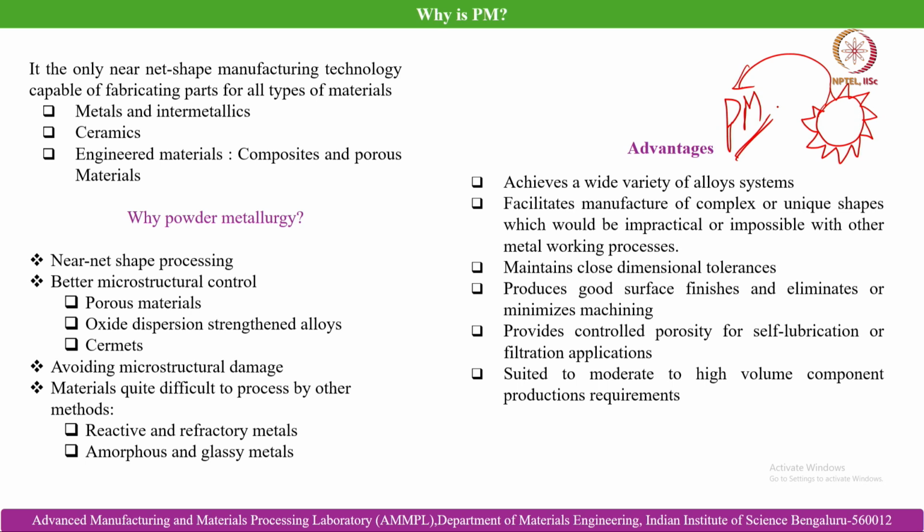In a much more economical manner. So the benefits are economic, and also in terms of properties, because we are talking about an additive route of manufacturing, so there is minimal wastage, and also better control of the microstructural morphology, and thereby we can control the properties. This is an example that you can take for understanding why we will go for PM. But it is not all advantage, every process has some disadvantages also, because there is a size effect in PM.